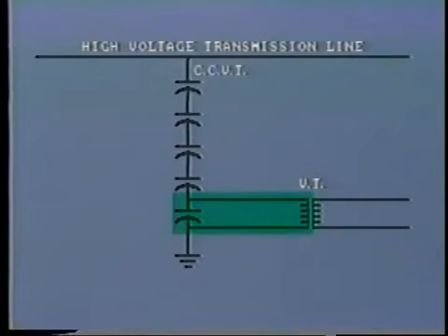That is at lower voltage, but still representative of primary voltage. Now, the VT does not suffer the same problem of saturation as the CT. This is because faults usually cause a voltage reduction, not an increase. In the case of a system disturbance, the system voltage may rise, but certainly not sufficient to bring the VT to saturation.